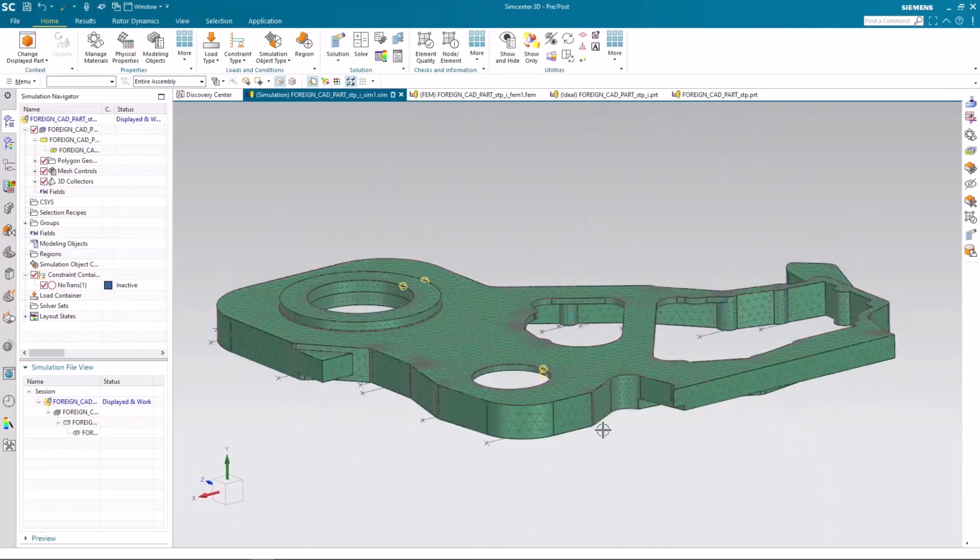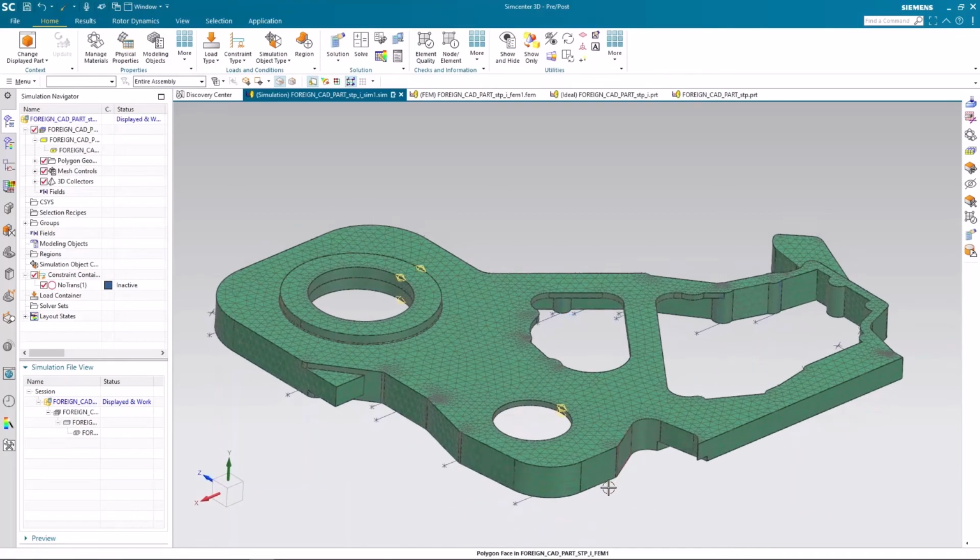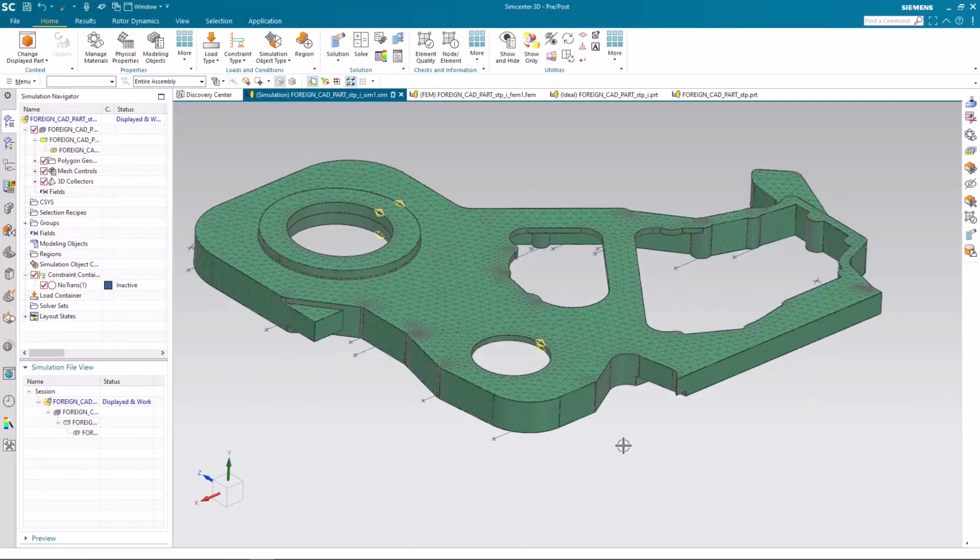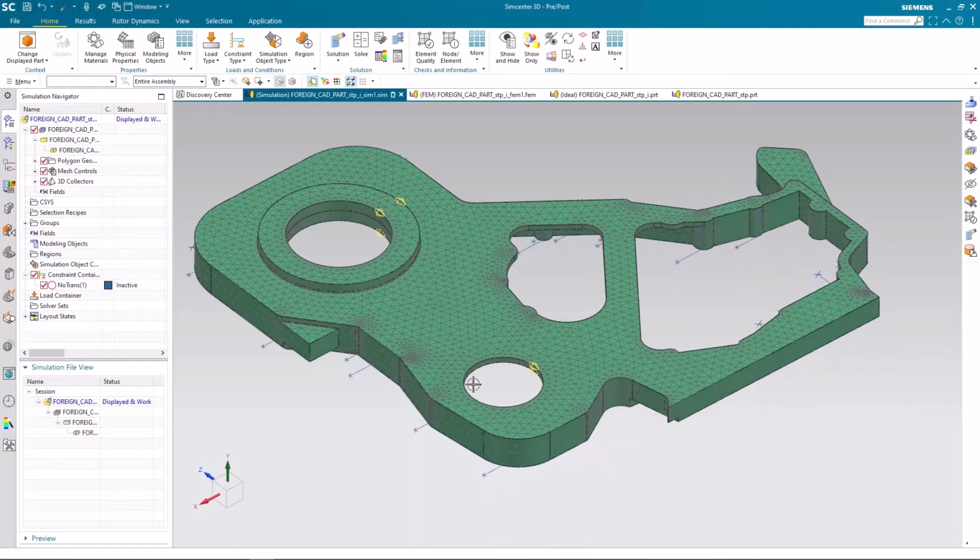I know that there is a shaft that passes through this circular hole, and the power transmission shaft will mount on some type of bearing, so we know that a bearing has a stiffer material than aluminium. So I want this circular geometry to remain circular, because during the loading condition this circular geometry remains circular.